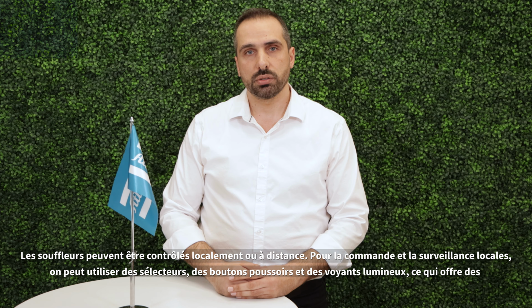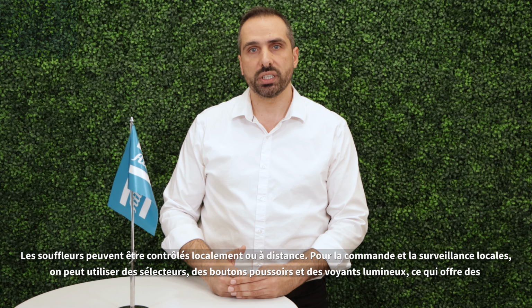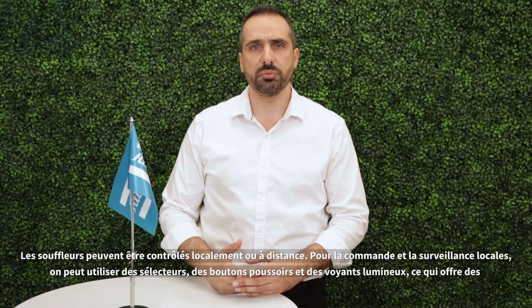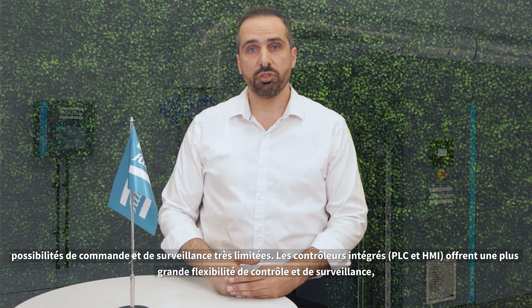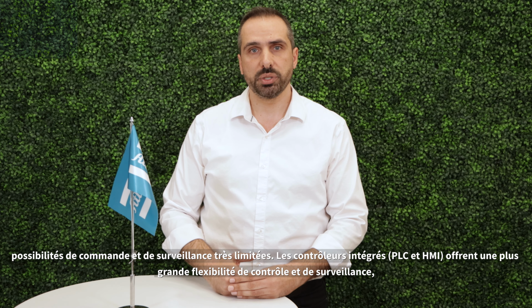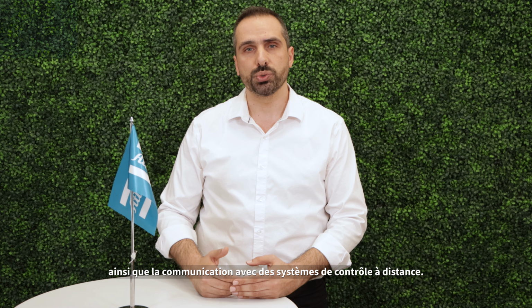Fourth is the controller. Blowers can be controlled locally or remotely. For local control and monitoring, selector switches, push buttons, and indication lights can be used, which offers very limited control and monitoring capabilities. Integrated controllers, PLC and HMIs, provide additional control and monitoring flexibility as well as communication with remote control systems.